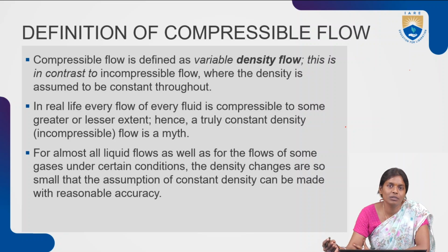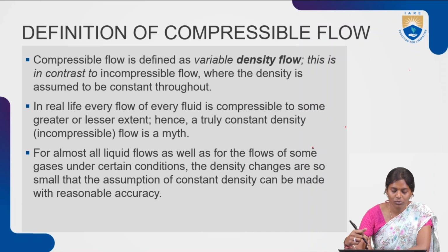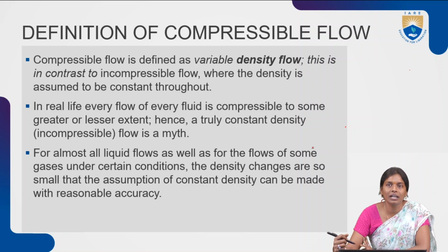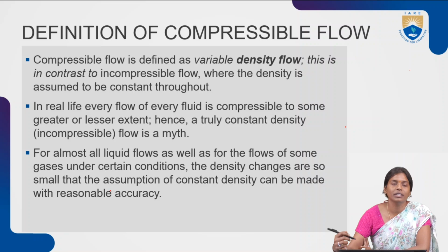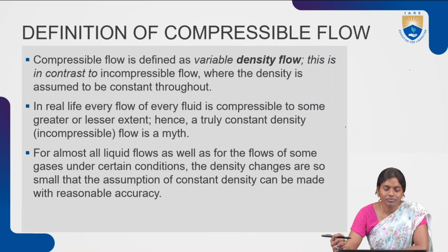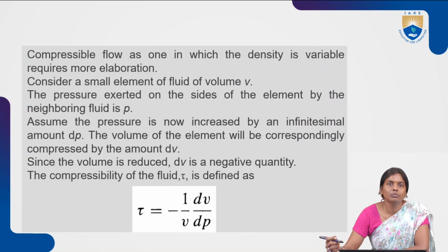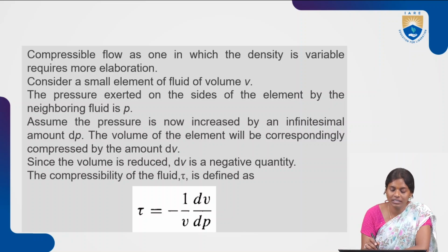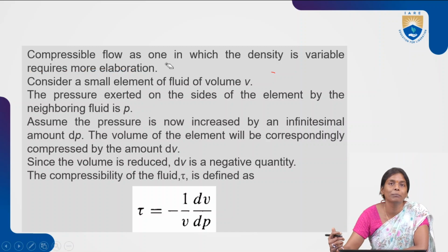Even though there is a change in pressure, the change in density is very minute. For all liquids, under certain conditions, the density changes are very small, so the assumption of constant density can be made with reasonable accuracy. So compressible flow is nothing but flow where density is a variable, which requires more elaboration.